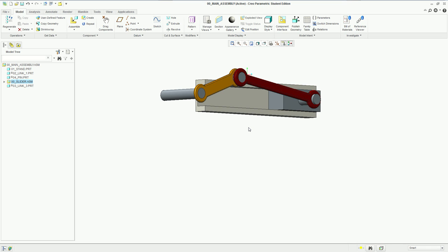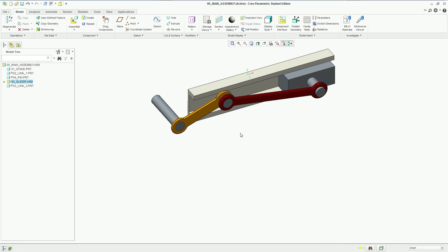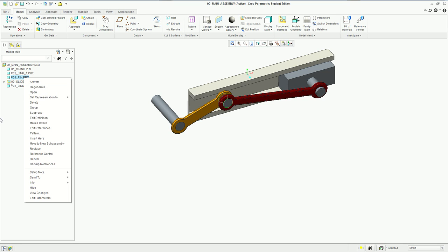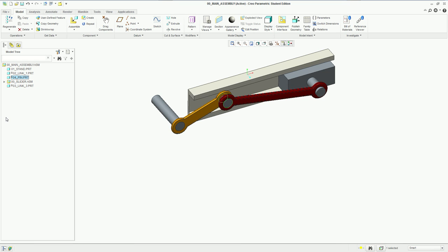Now we're going to do some kinematic and dynamic analysis. Before I do though, let me show you a little thing that you need to do before you do dynamic analysis. Before even I do that, let me just explain what kinematic and dynamic analysis is. Kinematic analysis allows you to calculate position, velocity, and acceleration. So if you think back to physics, it essentially solves kinematic equations for you. But then the dynamic analysis gives you force values. And it gives you reaction forces in all these pin connections we made.